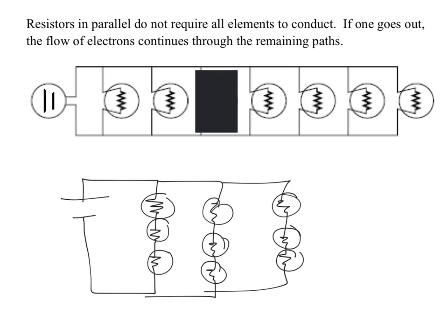It's both, very good. These are new Christmas lights. If you notice, if a Christmas light goes out, about 5 or 6 sometimes go out around it, because you have a bunch of little series circuits that are parallel together. That's physically what's happening here. So one bulb goes out, you see a strand of 3 or 4 go out, but the others all remain. If I take out this bulb right here, that entire circuit area goes out. But the rest are still good.